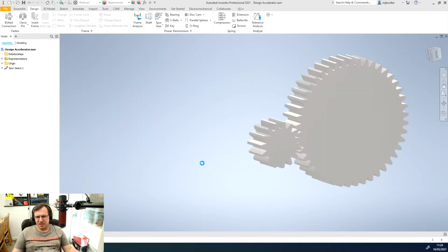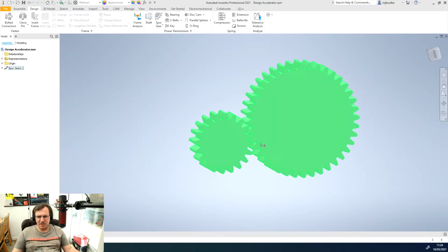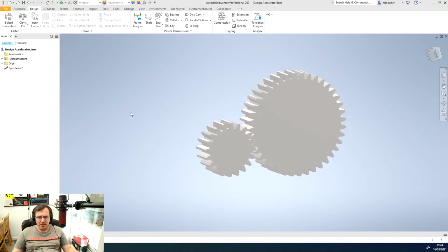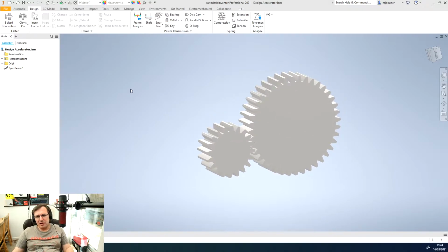And then we'll just click OK. And obviously it changes the size of the gearing depending on the gear ratio, and it also updates the number of teeth for that particular gear itself. So we'll leave it at 2:1. So we now need to look at drawing our shafts and creating our two shafts.